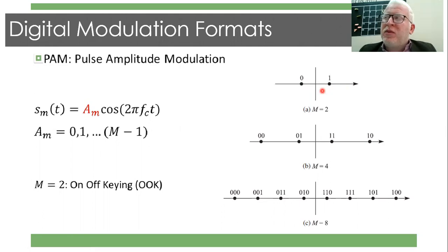So, for a binary amplitude modulation, you have a symbol which is either 1 or 2. Then you have two states, as you can see here. The first with a positive amplitude and the second with a negative amplitude. By the way, this is typically correct whenever you are doing binary phase shift keying, as you have one in-phase and one anti-phase symbol.